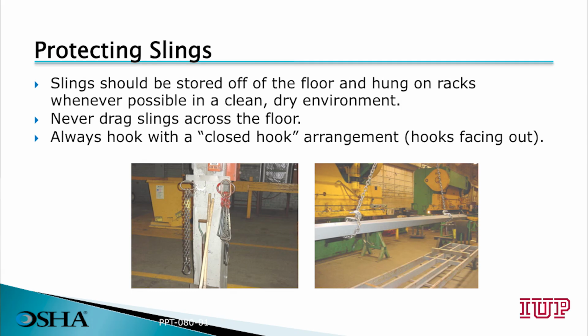How do we protect our slings? Slings should always be stored off the floor and hung on racks in a clean and dry environment. And never drag a sling across the floor. When rigging, you always hook with a closed hook arrangement where the hook tips are facing outward.